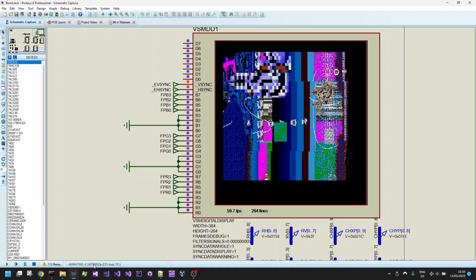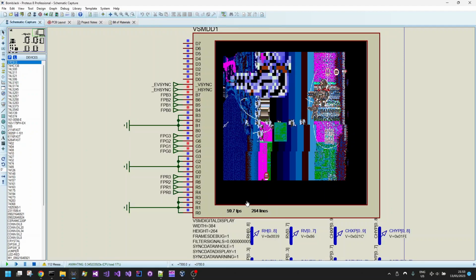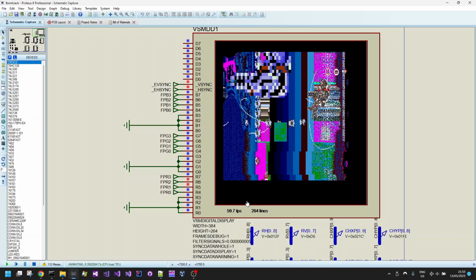It's creeping up, and the rendered raster position is creeping down the screen. So each frame, sometimes the test data will wait for a particular horizontal and vertical position before updating the sprite registers. We're just basically animating the data by updating the various different internal registers and palette entries and so forth. So all of this is just generating output frames that we check for being correct later on.